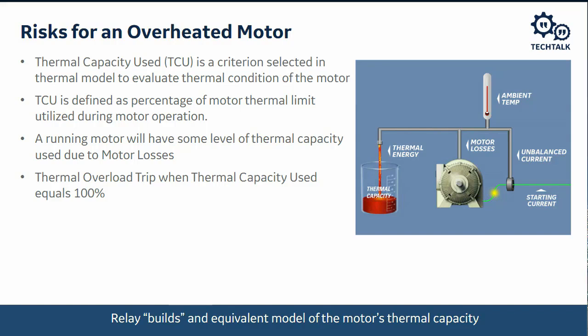It will model that based on the unbalance of the current. And then you really need to know if the cooling is available on the motor and if you have an unusually high ambient. And the motor thermal model can be biased with RTD biasing, and that would take care of an unusually high ambient or the loss of cooling on the motor.